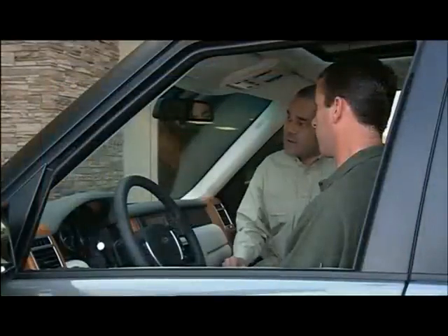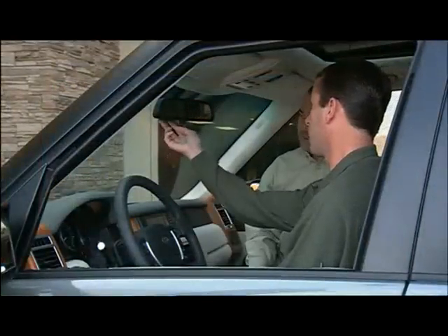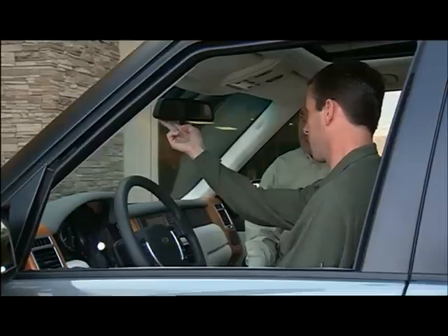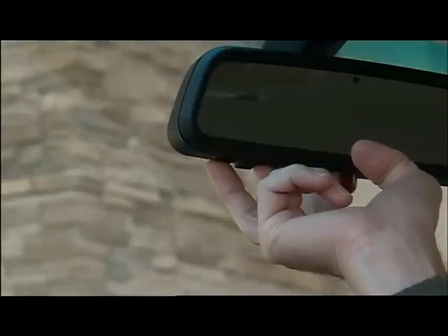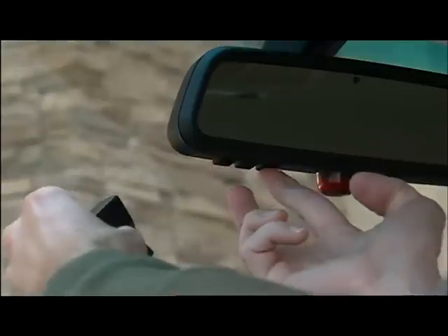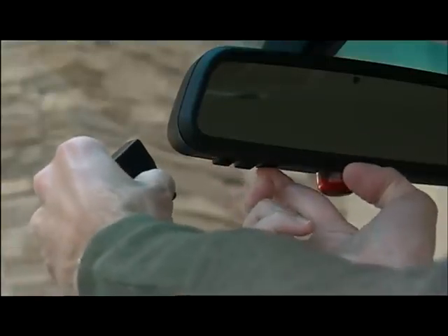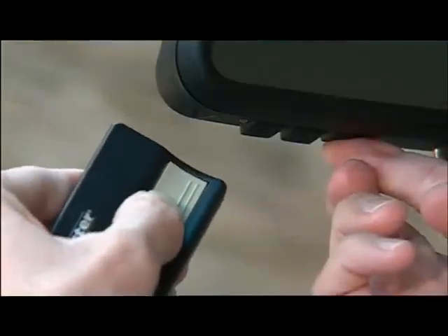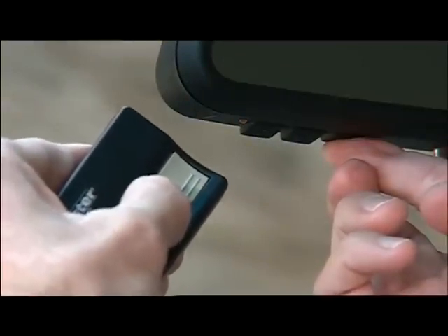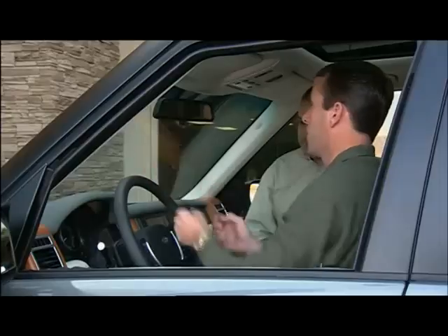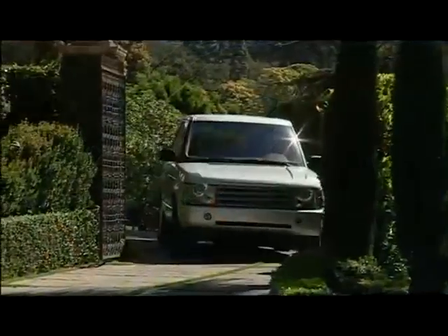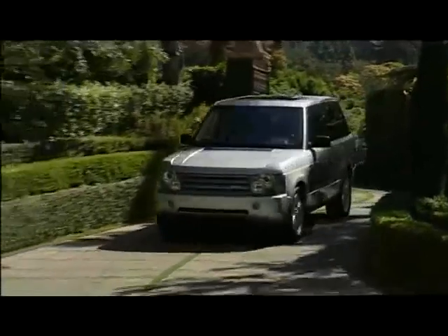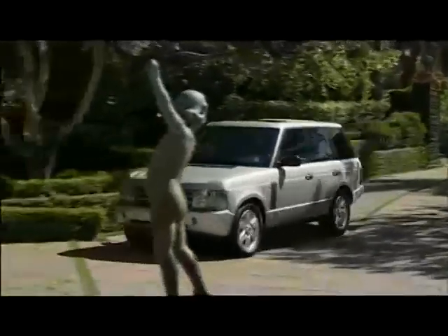The HomeLink transmitter is located on the rear view mirror and can be programmed to operate 3 garage doors or gates. Press the 2 outside buttons until the amber light flashes. Release. Hold the end of your transmitter against the HomeLink transmitter. Press the handheld button and the desired HomeLink button and hold until the light flashes, first slowly, then quickly. This confirms that the button is programmed. Refer to your handbook for more options, including setting HomeLink for rolling codes.